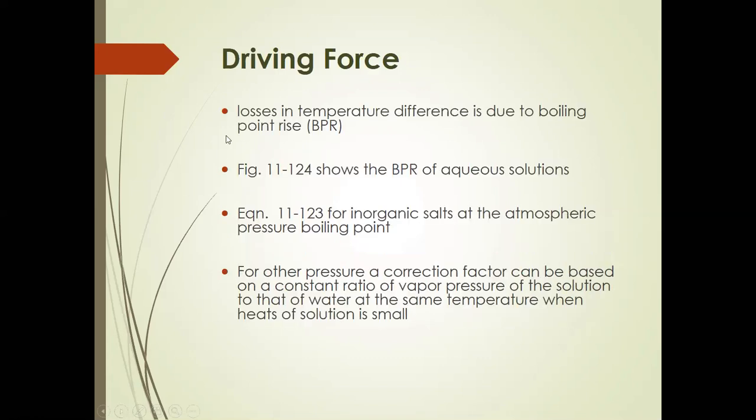Now, this driving force will lose its essence or will not be capitalized on if the boiling temperature of the feed inside the evaporator is increased. Why is that? We're going to subtract in the first place the boiling point temperature of the solution from the temperature of the steam.